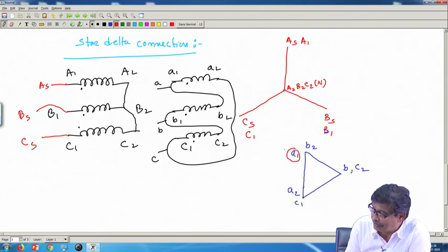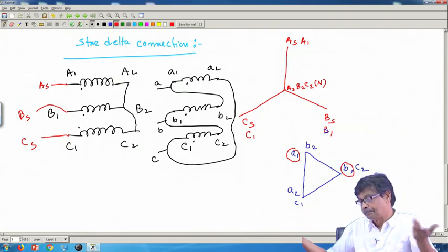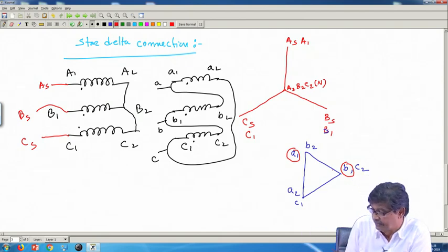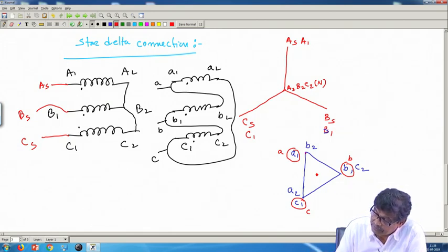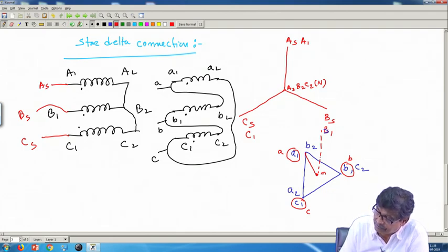And then I am telling, mark this, please follow the instructions carefully, so that you will never make mistake while working with a 3-phase transformer in the laboratory or at the site. So, A1 B1 C1, these are the things, this is A, this is my B, this is C. So, balanced 3-phase voltage will be obtained. So, here is the artificial neutral, because delta connection, no neutral. So, A phase voltage with respect to this neutral, and A phase voltage of the primary is this vertical line, therefore, it is 30 degree.